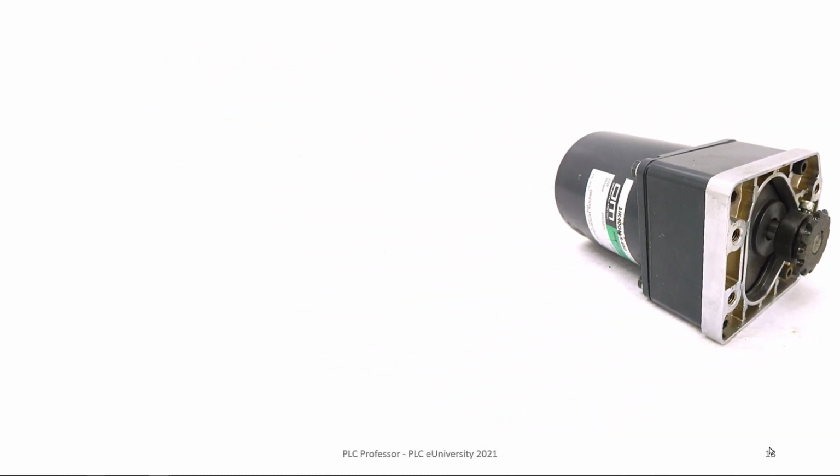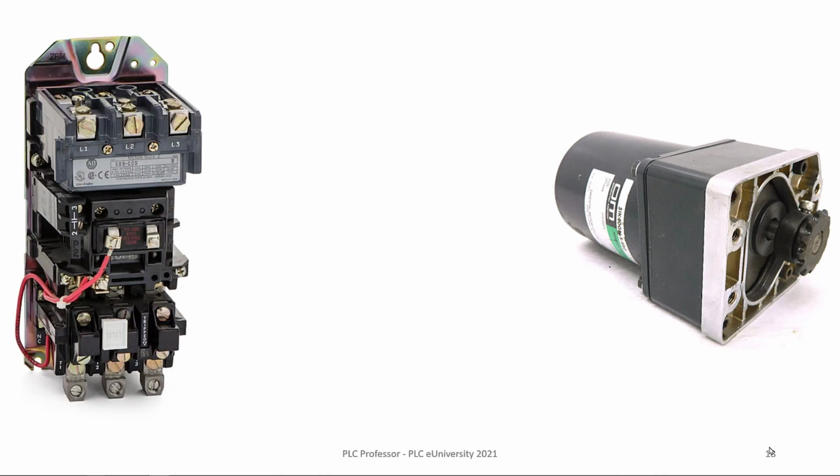Okay, the motor is controlled by something that kind of resembles a relay. The reason this is not a relay, two reasons. One is when you get into larger current flows, they tend to call them contactors instead of relays. Plus, this one has motor overloads. When you look down at the bottom of it, you'll see a reset button and you'll see a tripped indicator. Well, this is a three-phase relay type switch. So you have power coming in L1, L2, and L3, and then out of the bottom you have three conductors going to the three-phase motor, T1, T2, and T3.